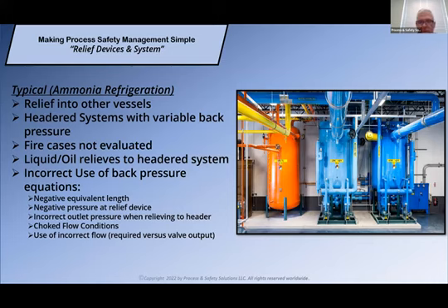So typically drains get opened very frequently, and you could have a number of feet of liquid sitting on top of that relief valve, rendering it inoperable as a result.